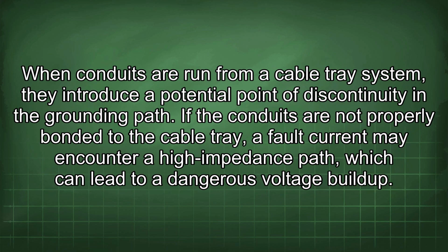When conduits are run from a cable tray system, they introduce a potential point of discontinuity in the grounding path. If the conduits are not properly bonded to the cable tray, a fault current may encounter a high impedance path, which can lead to a dangerous voltage buildup.